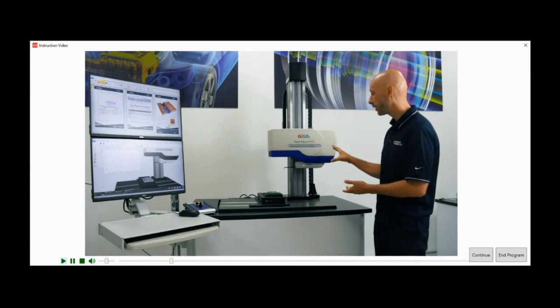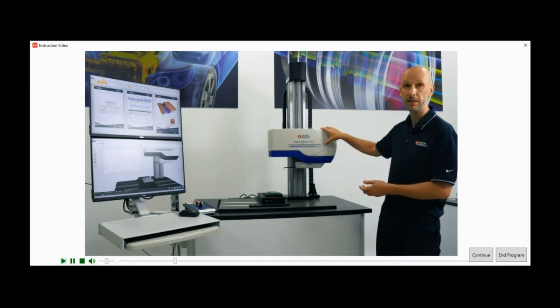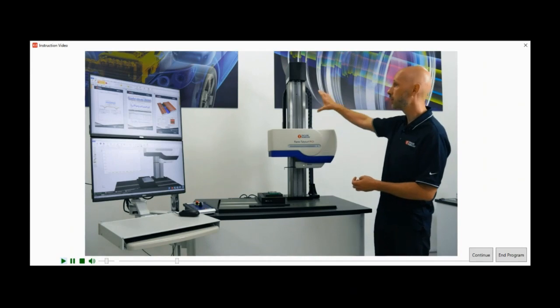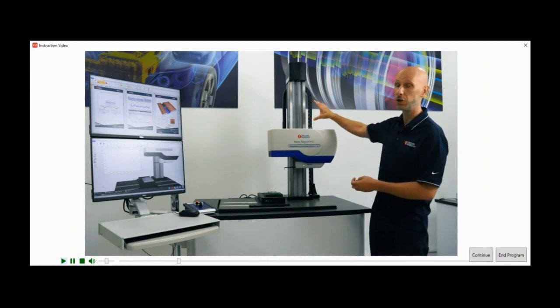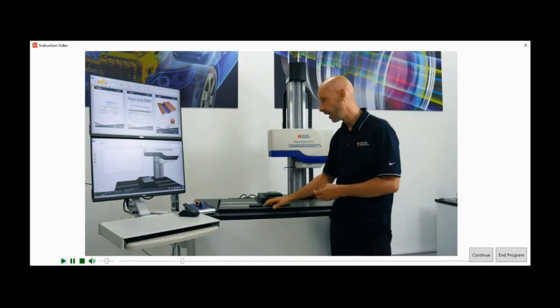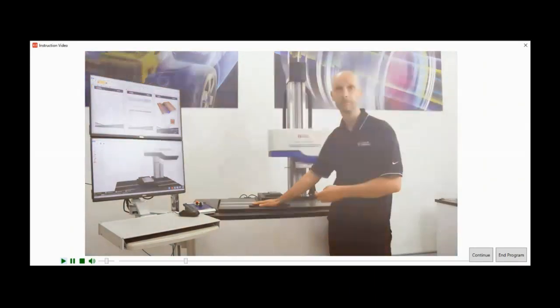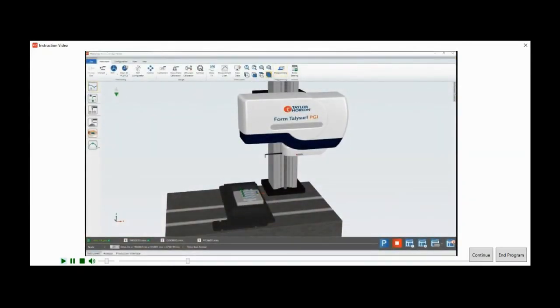This particular system is a dual bias system with a 200mm traverse unit, 700mm high precision column, and we currently have it with the instrument surround and the Y stage capability for measuring 3D. The software is split into three main areas. They are the instrument view for control, for movement, for calibration, and also programming.